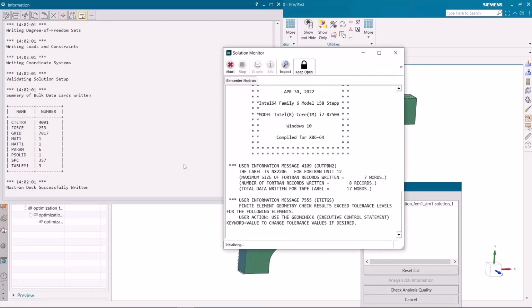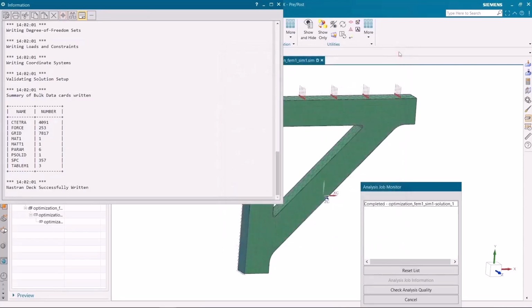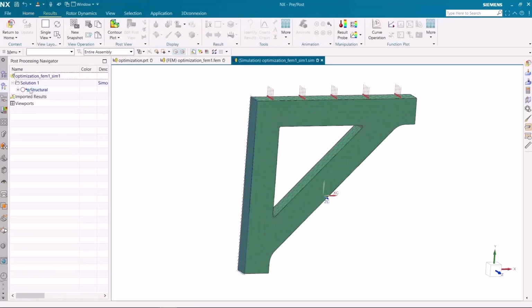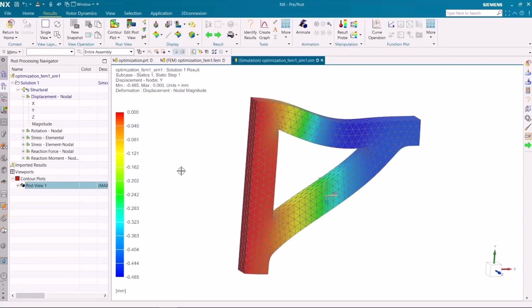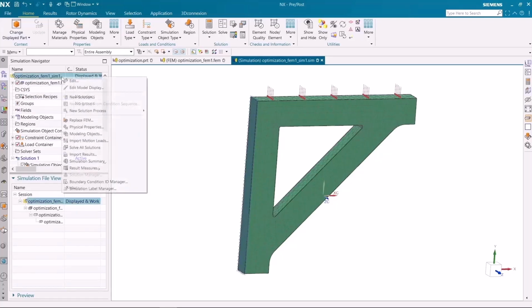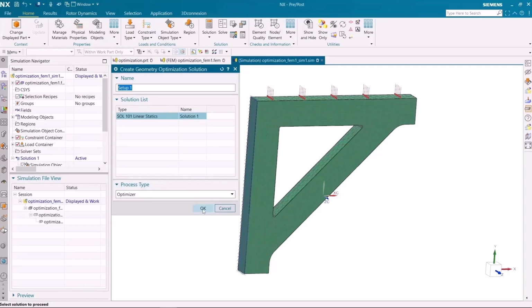and boundary condition. The design criteria for this bracket that it should not deflect more than 1 millimeter in negative y direction. So let's review that what we are getting as per this load and boundary condition for this particular design. So here you can see that maximum deflection in negative y direction is about 0.485 millimeter.